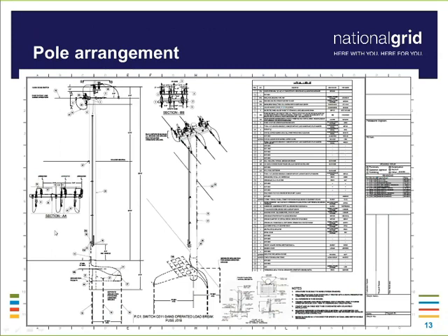So giving a top view of that pole, I'm sorry, that's an exploded side view. Now that's an exploded side view from a different angle, and that angle gives us more information that you cannot quite see from that side profile of the pole. That gives us further detail as to the equipment arrangements on the crossarms, and the spatial relationships associated with that equipment as well. And then we move over on the page, and there's another section, D-D, that does give the top view. Now that top view is also important because, again, it gives us the spatial relationships.